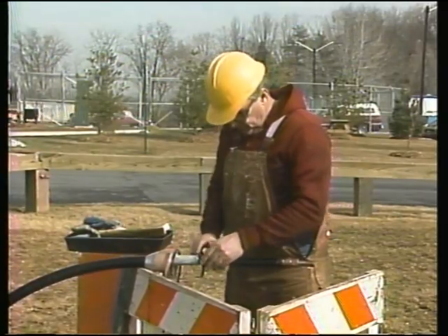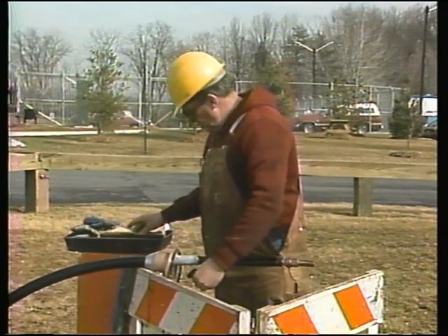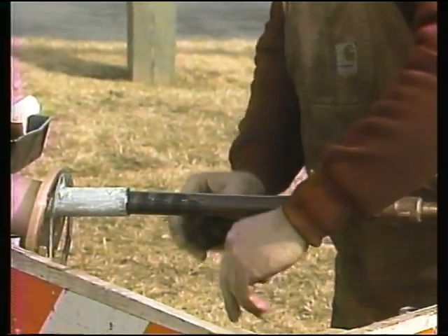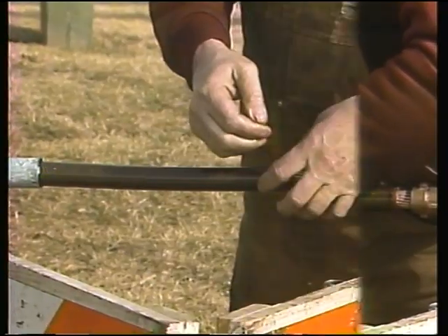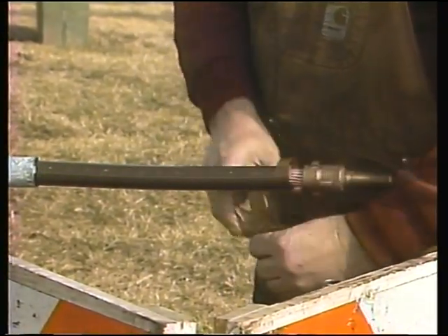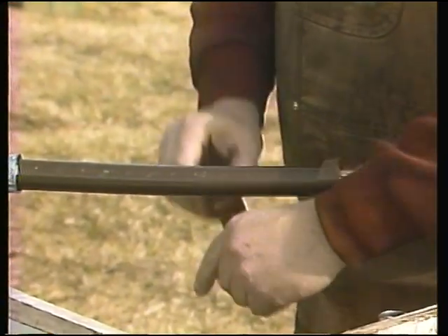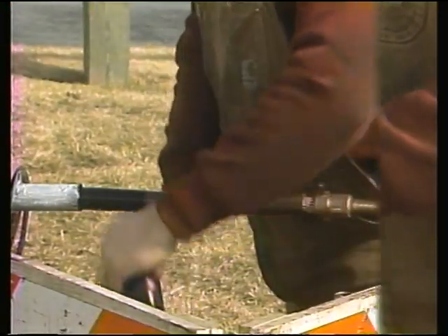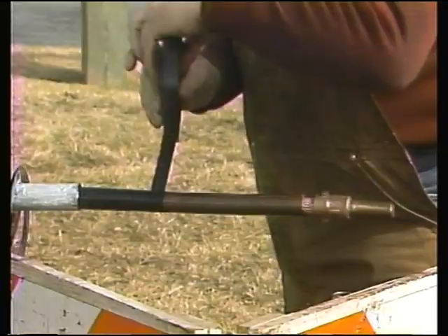After repositioning the cable and installing the terminator housing, the workman removes the protective tape layer and the semiconductive insulation shield. The top layer of the paper insulation is also removed. This ensures that there won't be any semiconductive materials left on the paper insulation. The top layer of insulation is replaced with insulating tape.